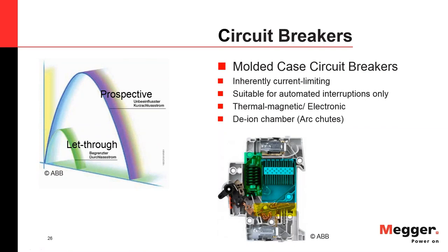So they can sense the fault current, and they can trip. The user or a technician or whoever has to go to the breaker after a trip to reset it and close it in again. Airframe circuit breakers are typically the same way, but there are also models that have a closing coil, like medium voltage circuit breakers, and can be remotely closed as well.